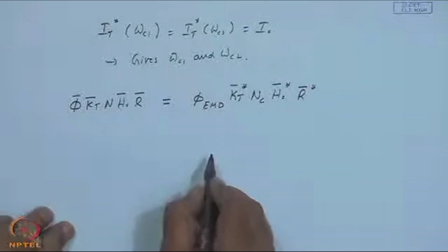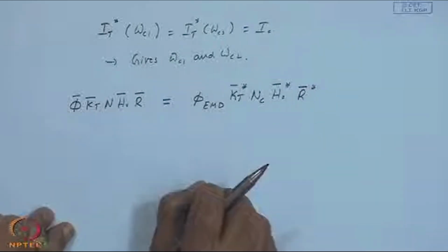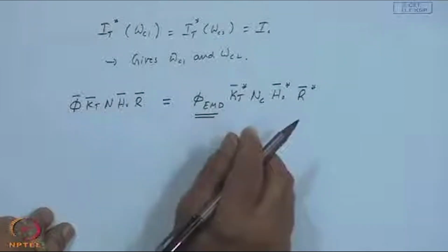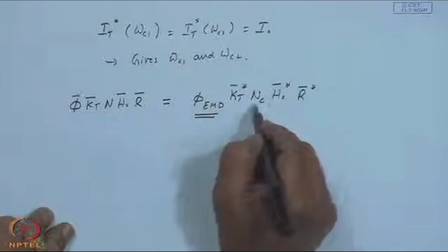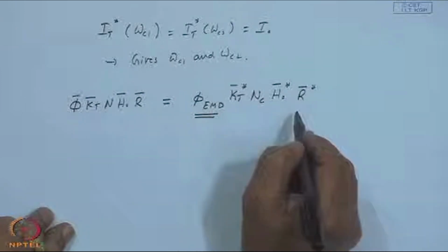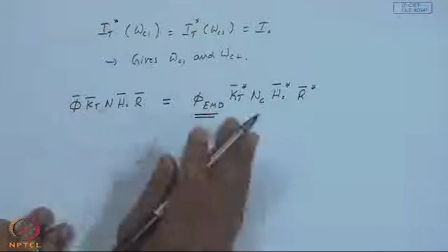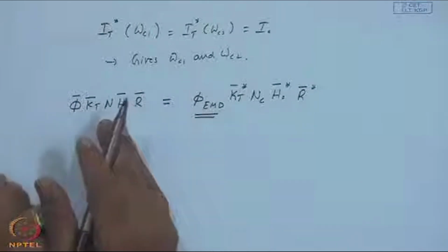What we realized is the solar radiation available above the critical level, be it based upon the equivalent mean day of the average days with KT greater than KT minimum, or all the days with the monthly average daily utilizability phi bar with corresponding n, should be equal, because the other days are always less than the critical level and they do not contribute to any solar radiation falling on the collector surface above the critical level.